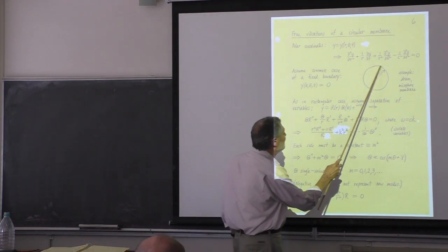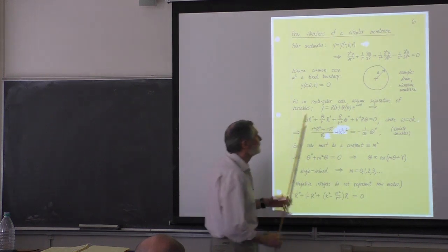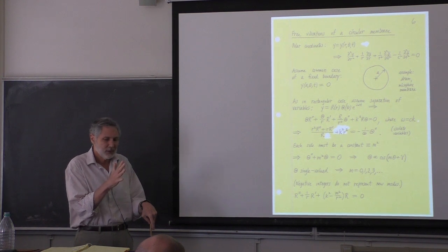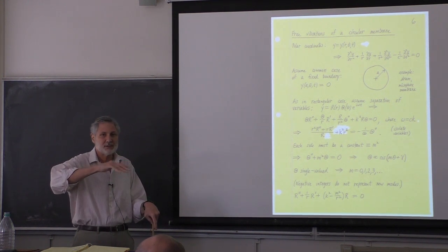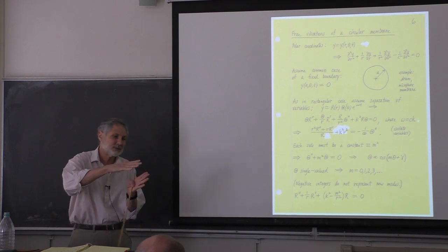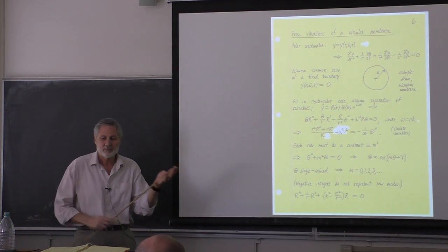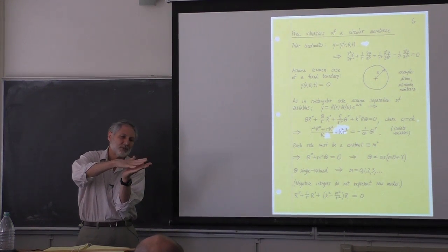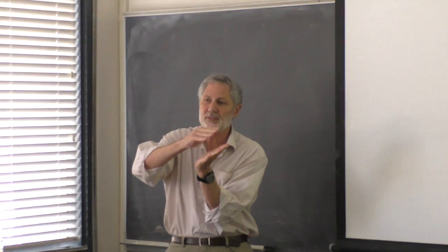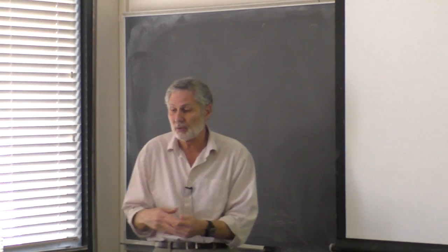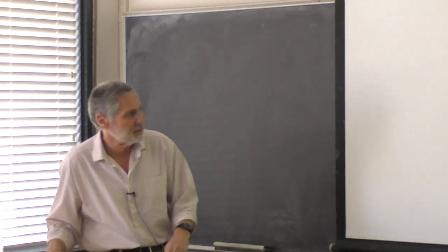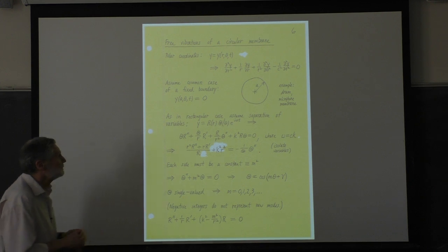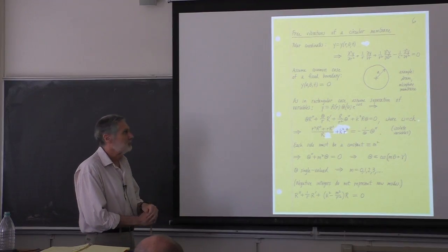We're going to do the problem where it's fixed here. We'll do another problem in the homework, okay? And a sound comes and excites this membrane. The membrane forms one plate of a capacitor, and then there's another fixed plate here. So a sound wave changes the capacitance here, and the charge is kept constant, so the voltage changes. So we'll get into this in the transducers course. But anyway, I just want to mention to you, this is one application of these modes of a membrane.